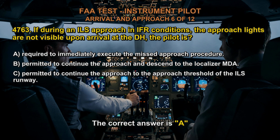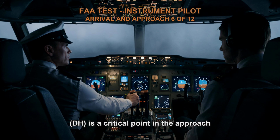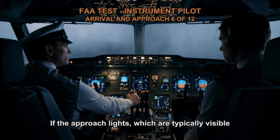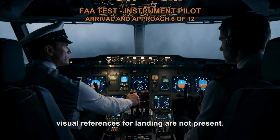The correct answer is A. When conducting an ILS approach, the decision height, DH, is a critical point in the approach where the pilot must make a decision to either continue the approach or execute a missed approach. If the approach lights, which are typically visible at or near the DH, are not visible to the pilot, it indicates that the required visual references for landing are not present.